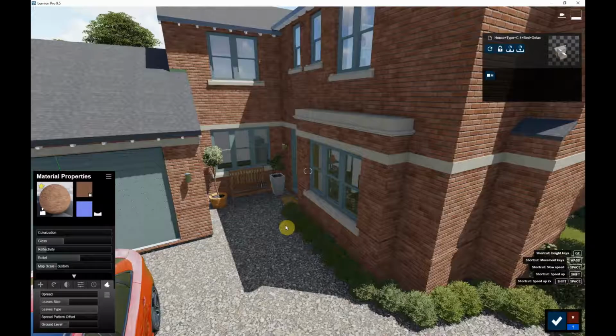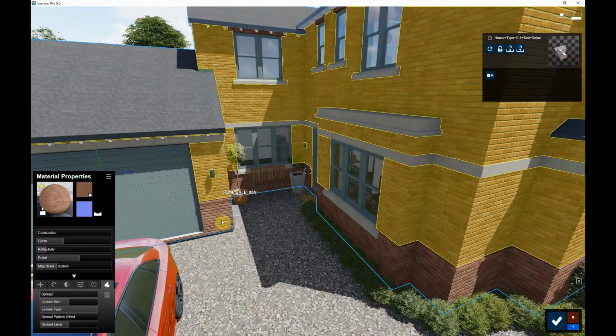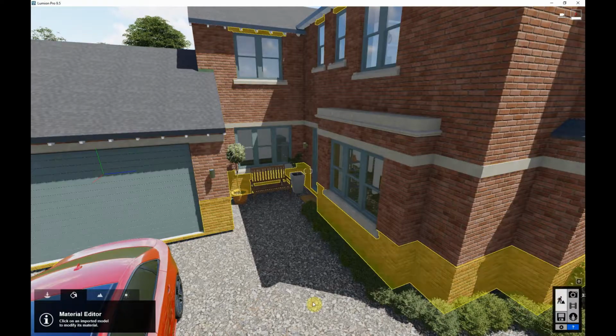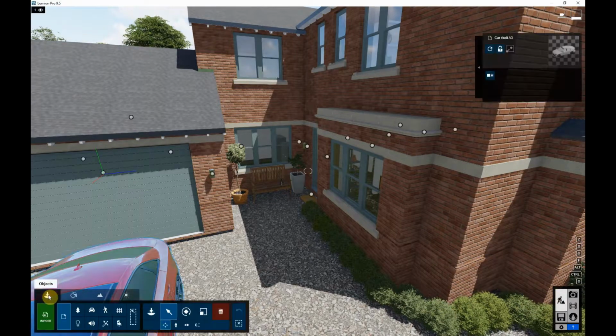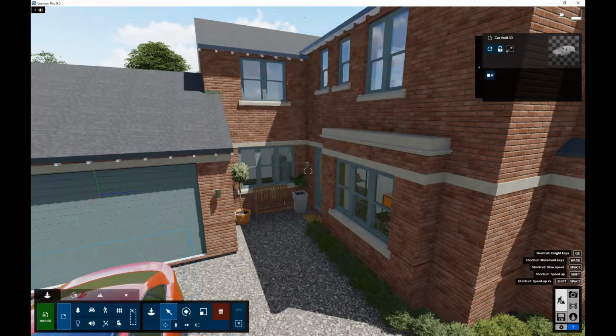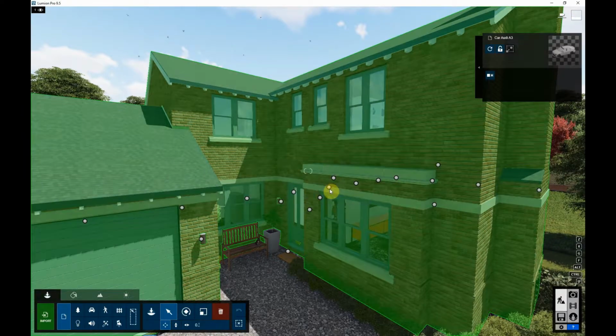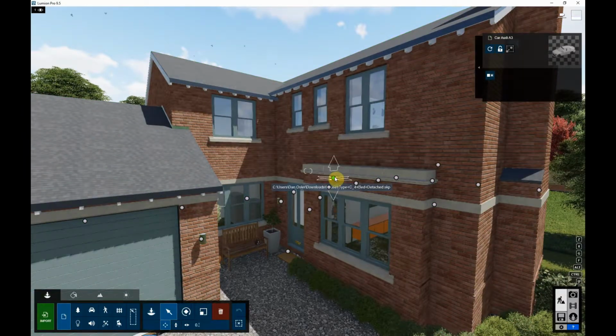So next, after you've adjusted and made all the materials how you want them to be, you would look to add objects into your scene. So back to where you did the standard import for your main model, you can then view the eight sections of the libraries here. So go through nature, transport, people and animals, outdoor, indoor, effects, sound, and lights and utilities. As you can see here popping up on the screen, the import section has the nodes to just dictate where all of the objects are.